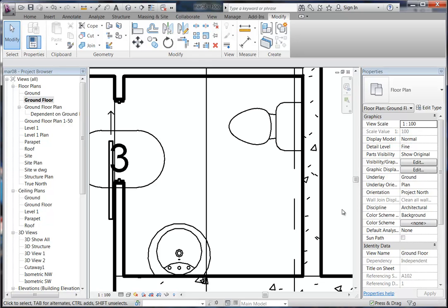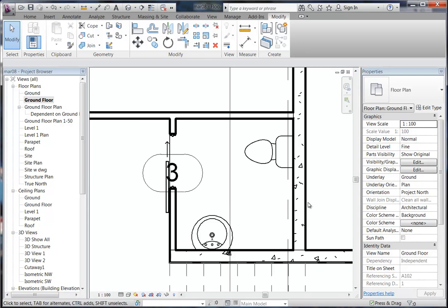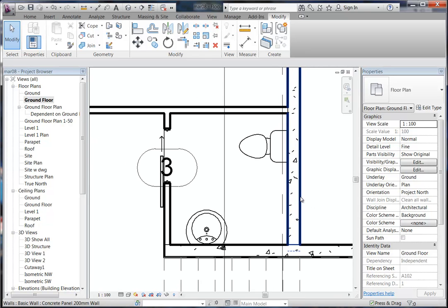And this often happens if people haven't made an allowance for the tiles before laying the slab, or enough of an allowance compared to the main floor lining. The tiles will sometimes be raised above the main floor lining. It just means they haven't actually planned it out, but that does happen. Or sometimes if the floor linings are a similar thickness. It depends how you want to do it. I mean, you could always make this one a bit thicker anyway and raise it up, but it's nice if they're at the same height, and you can easily achieve that.